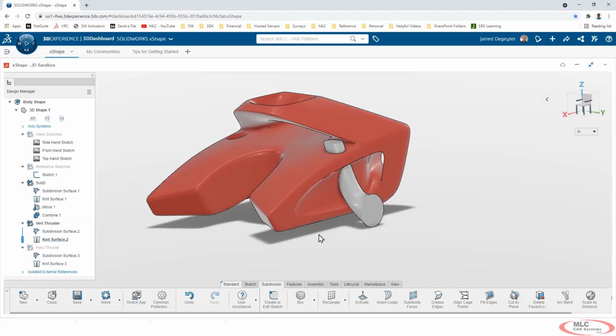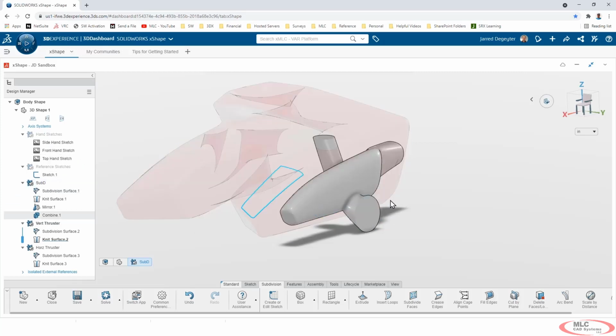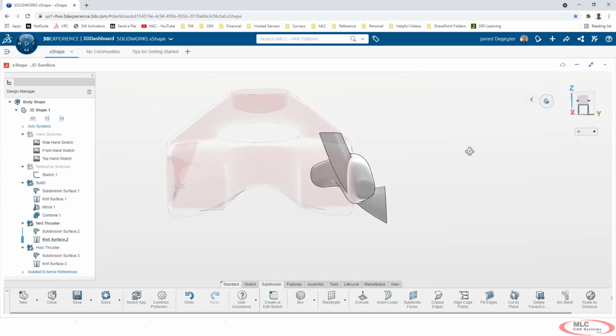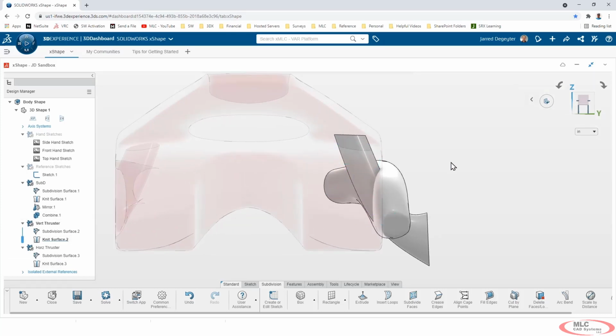So I'm going to show the bodies that we used to subtract and create those two cavities. And notice how both of those bodies are in their own ordered geometric set. Placing them in an ordered geometric set breaks the dependency between these bodies and any other feature. So there's no longer any other type of chronological solve order going on in this part.